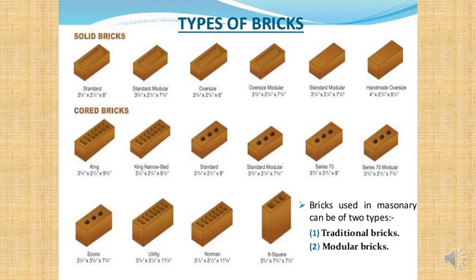So you can see that frogs were quite popular for quite some time, but these days increasingly cored bricks are becoming very common. This is where you have a frog or a cavity that goes all the way through the block. So there's actually a hollow section. And this is often arranged in rows, as you see there, or it could be small cylindrical holes drilled through. There is another advantage with this, which I will get to later. It's got something to do with reinforcement. Think about that.